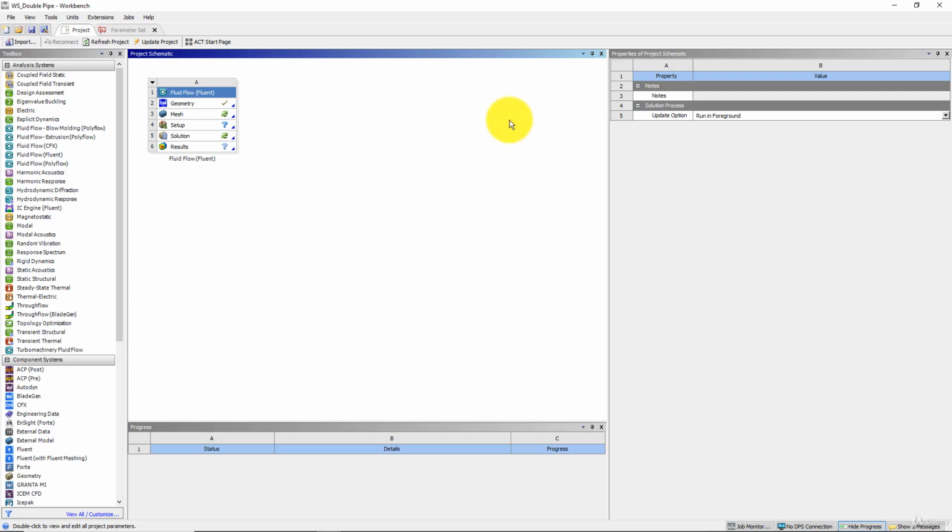You don't have to stop the solution, change the parameters and boundary conditions, and then run the solution again. This will be done automatically. But in the serial case, the first case finishes and then the second case starts, and similarly for the further design points. So this will take some time, but if you have the licenses and more CPU power, you can run them in parallel.